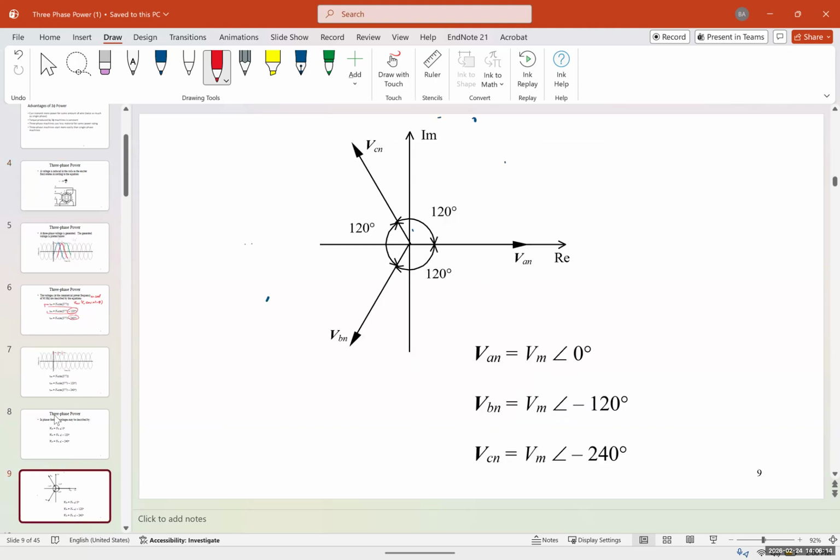So to go from that, we have to change the sequence. So instead of going this way, the phases, it should go the opposite way. Okay? So what we do is just flip two phases. So instead of connecting ABC, we do ACB. So flipping two switch, we flip the rotation, and we go from the left turn to right turn.